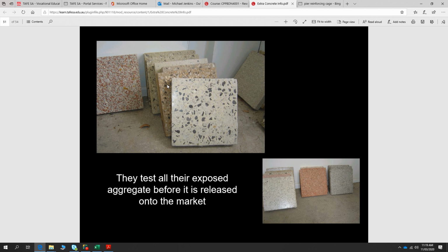That's done after it's been troweled off. You spray it with a mixture of water and sugar. You just buy it. I forgot what they call it, but it's just water and sugar almost. Then leave it for a bit, and then just spray it off with a high pressure hose. It depends how good you are. You can just spray it off with a normal hose if you get enough pressure on it.